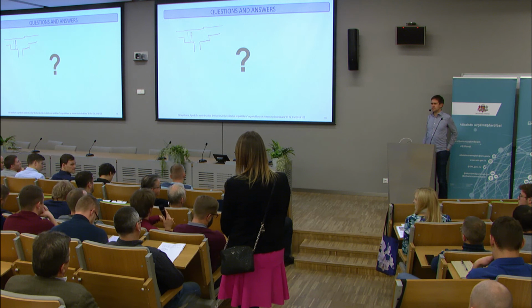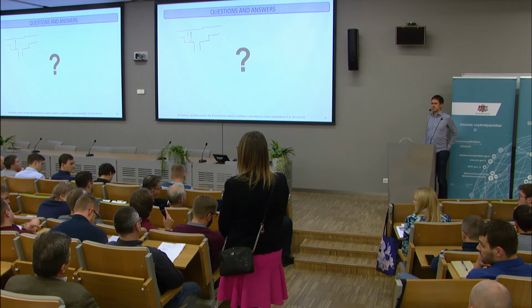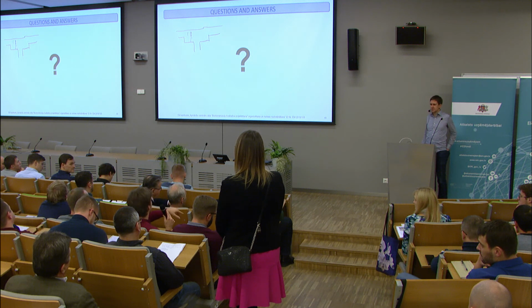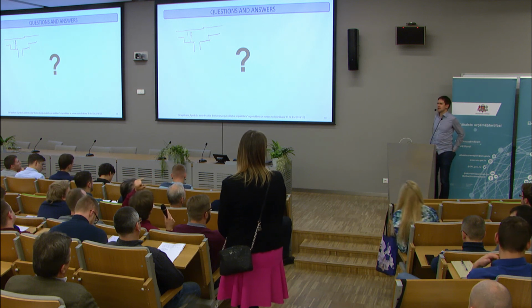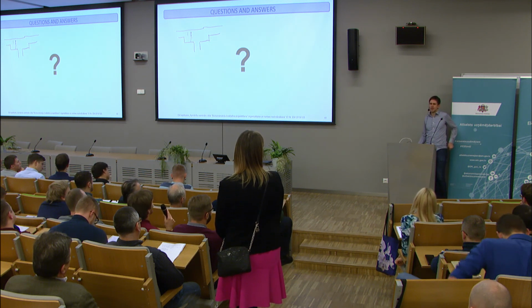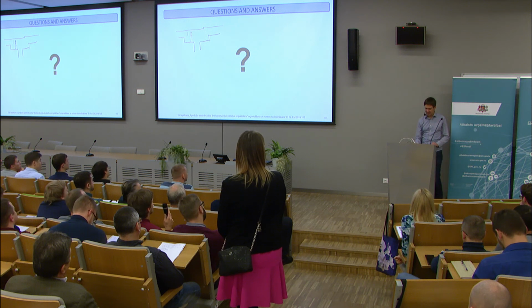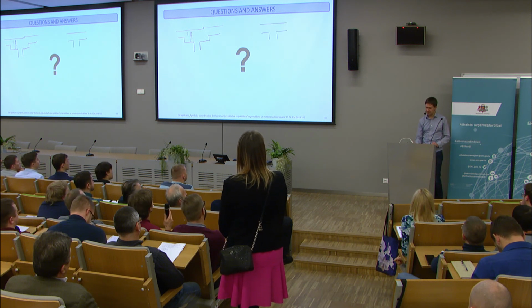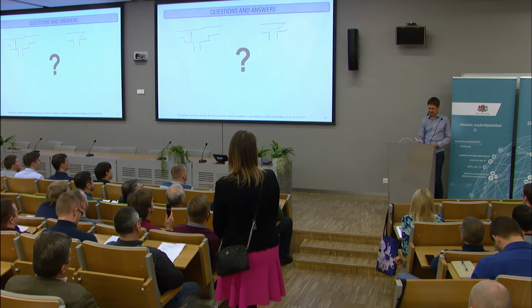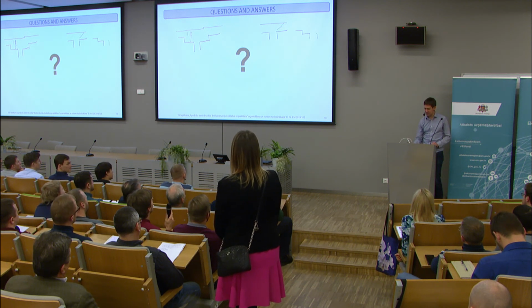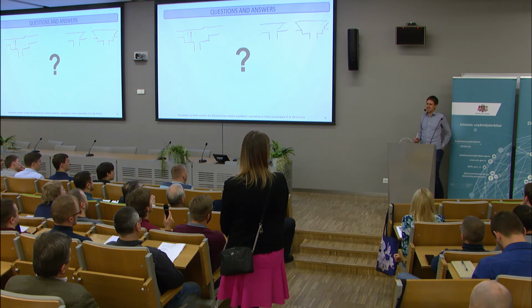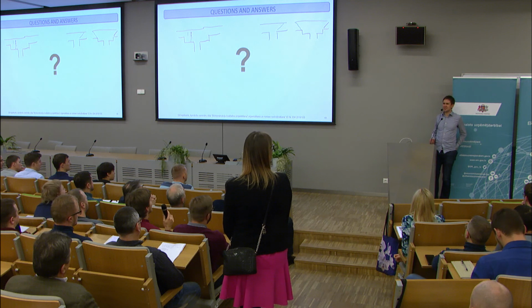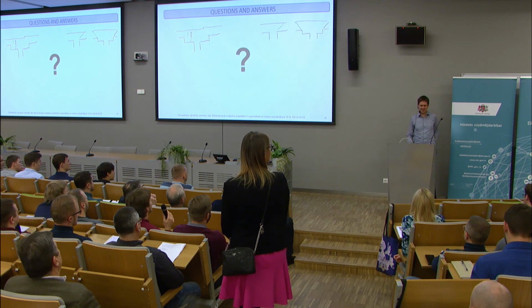I think that for the new model code, inevitably you will have to put the shear bars in the capital. Because the problem with punching without shear reinforcement is that it's very brittle. And if we put capitals, it's still as brittle as it was. It would just happen outside of the capitals. So the idea of the code is to force engineers to more ductile failure modes. So they don't want to encourage building slabs without shear reinforcement.